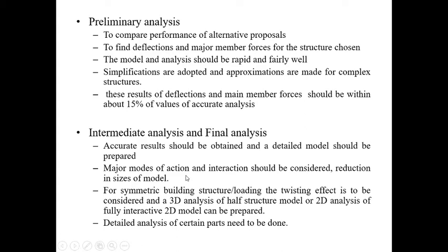And the major modes of action and the interaction should be considered. So where the loading is acting, how the action is taking place, what is the interaction between the beam and column. All that should be considered while doing this modeling, and the reduction in the sizes of the model can be done here. Then in this case, the columns, beams and the bracing members will be represented by beam elements, while the shear wall core components may be represented by membrane elements. So we give the representation of the actual model to the model which we are analyzing.